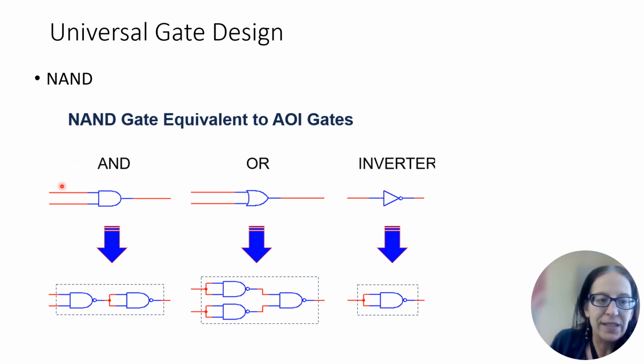Next simplest one is the AND. Well, an AND is a NAND, except you don't want it inverted, so you have to invert it back. So you would run your two inputs through a NAND gate and then immediately through an inverter. Keep that in mind. With NAND gates, the AND is the easy one. The one that's more complicated is how do you get NAND gates to OR for you?